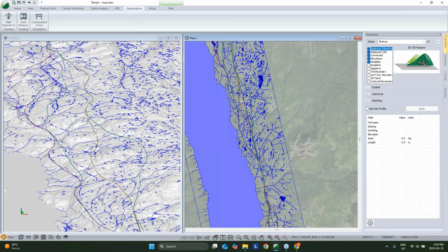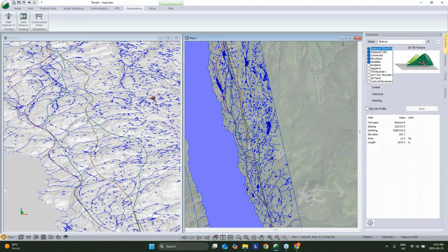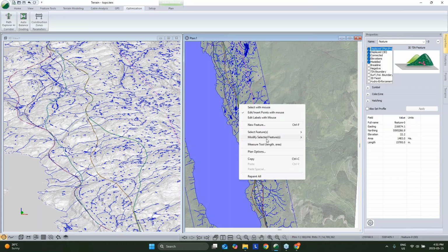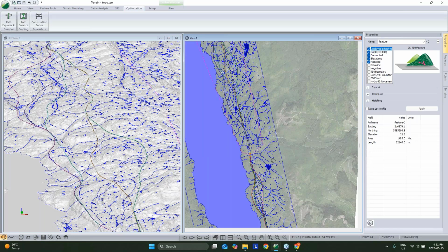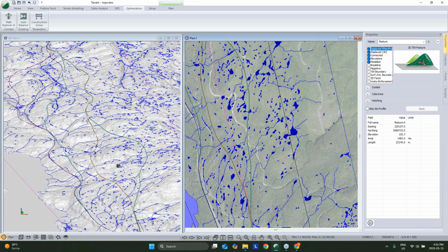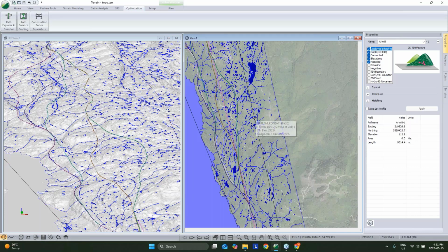Maybe for that second one, I wanted to run with a higher resolution, but I know I don't want to go outside of this line here. So I could draw that in and we could run Path Explorer on that solution. But we could have said that, well, this feature here is a no-go polyline, in which case it's not allowed to go across that line.